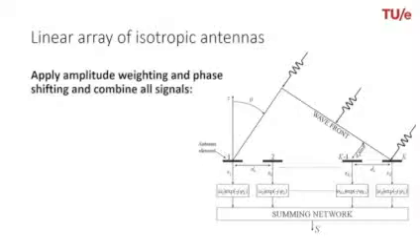Now, the next step is that these received signals by the individual elements are manipulated in the electronics. The electronics manipulate the amplitude and the phase. The amplitude manipulation can be done, for example, with a variable gain amplifier. And modifying the phase is done in a phase shifter or in a time delay unit. And after the manipulation, we sum all the signals in a coherent way.